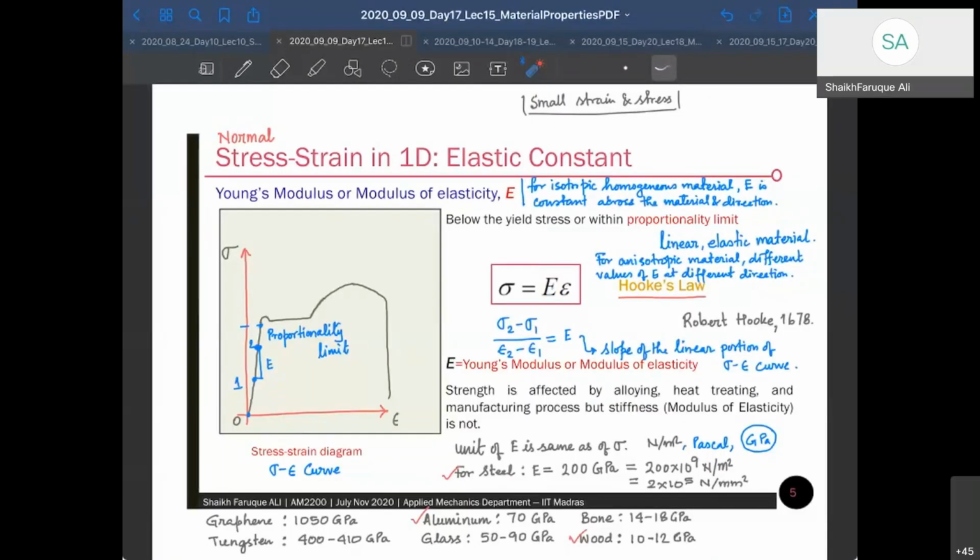All right, so we just saw how you get this curve for a ductile material. So can you tell me now, is this a ductile material or a brittle material? This is a ductile material. Okay. It shows a proper yield point, upper and lower, and it shows proper necking here and a flat region. If I had to draw on the same curve a brittle material, it would have been something like this.